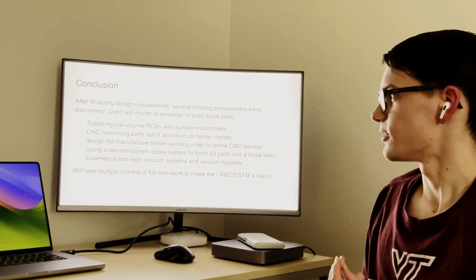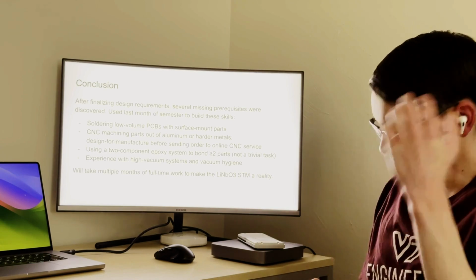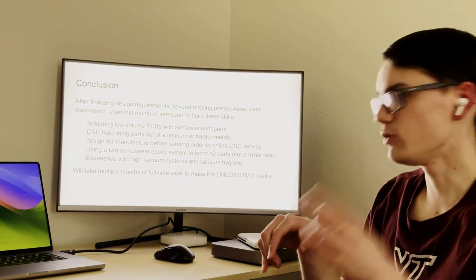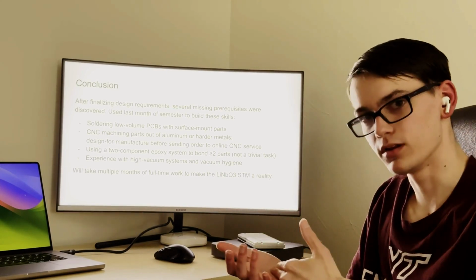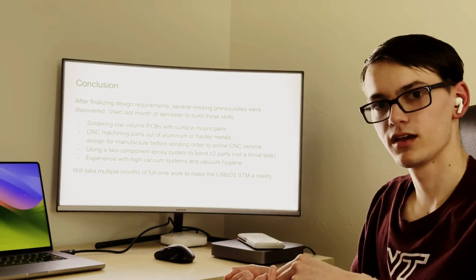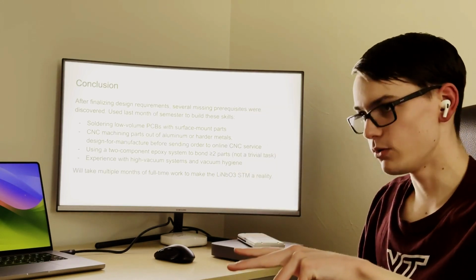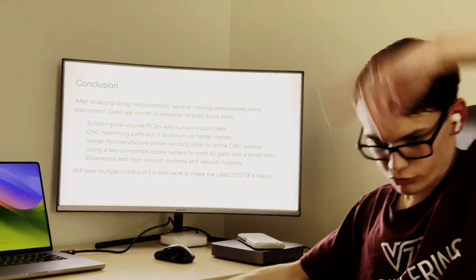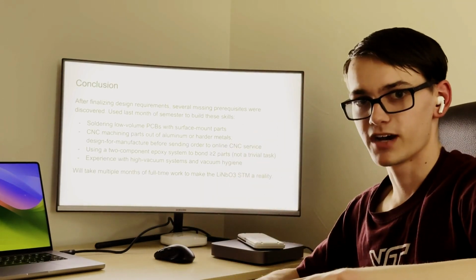And vacuum hygiene, I think, is also a really important thing. Just getting some lab experience: you need to have gloves, and you need to wash things off with nitrogen. If you talk near it, water droplets from your mouth will transport to your sample, and you don't want that to happen. So it's encouraged to not talk while you're handling samples before you put them in the vacuum chamber. Also, when you're moving things between chambers, you want to do it fast. You want to crank that lever fast to open the door and put it in, and then crank it back so the pressure doesn't rise really fast.